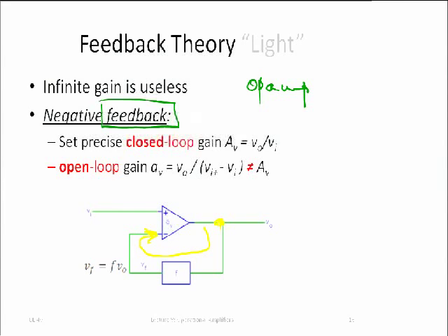This component here is an amplifier, right? Specifically, an operational amplifier. It's got a gain. What is the gain? Infinite, right? But this whole thing here is also an amplifier. It's also got an input, Vi. It's got an output V out, and it's got a gain that is V out over Vi, and the value, well, depends on all the stuff here, on this one and on this one, and it usually is not infinite, right? I mean, better not, otherwise we would have a useless circuit.